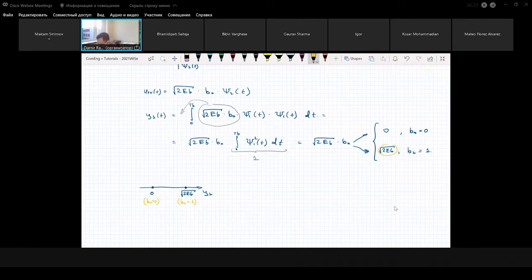There are three ways to determine the threshold: maximum likelihood, the Neyman-Pearson detector, and a third one I don't remember. But in our course, we assume a very simplified case, where symbols are statistically independent and the likelihood of observing any of them is the same for all symbols. As a result, our strategy is to place the threshold in the middle between the possible voltages.